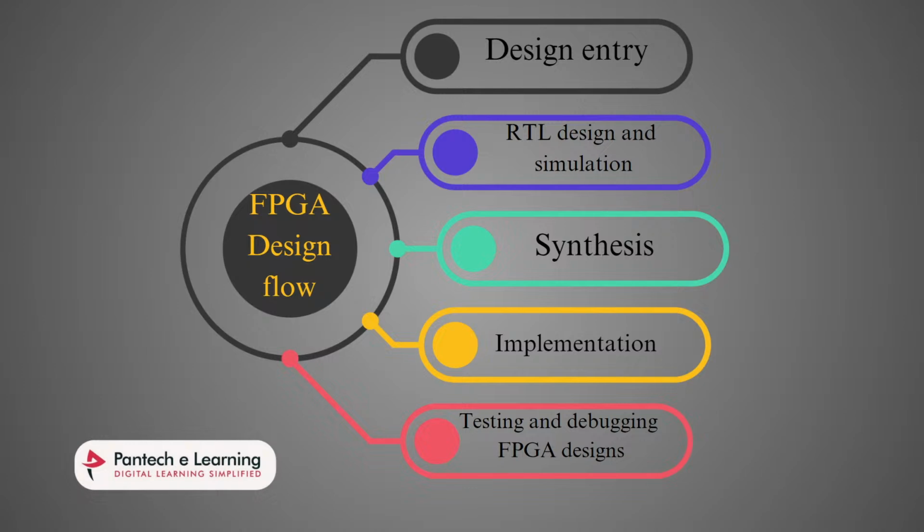The next stage is RTL design and simulation. A digital circuit's RTL design is an intermediate representation that concentrates on the data flow between the registers and the operations carried out on the data. It is based on the design and requirements of the FPGA. Before the synthesis and implementation phases, we have to ensure the functionality and performance of the design are confirmed via RTL simulation. As I already said, some industry tools like Xilinx Vivado have the simulation part also.